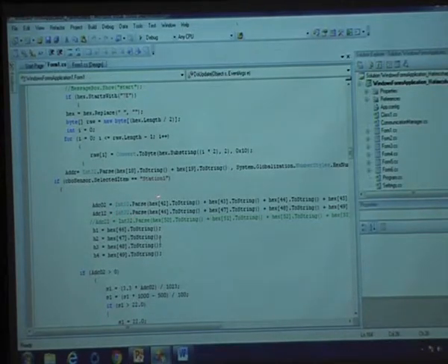Those pin number 20 values and pin number 19 values I have stored in my temporary variables called ADC02 and ADC12. The bytes 42, 43, 44, 45 correspond to pin number 20 only. That is equivalent to the temperature sensor value, the temperature sensor readings that you are getting here.